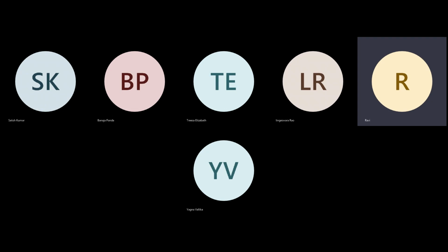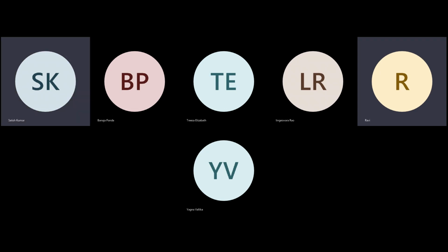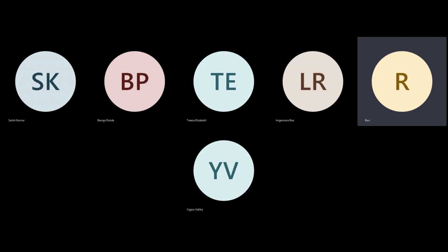triple height cell also. When you have a double height cell, you should understand that there is VDD in a double height cell, right? Because the top and bottom will be VDD, in between you will have ground. So you'll have to have 3 layers connectivity. In a triple height, it will be like two VSS, two VDD. You have to understand that these are in-between power connections, etc. So generally, double height cells you can expect, but there could be some specific cells which are triple height also possible.